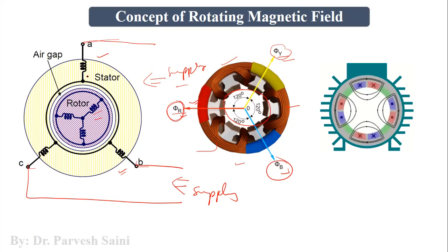All these phasors, as you can see here in this diagram, first one, these three windings are placed at 120 degrees apart from one another. They have a phase difference of 120 degrees, both on stator as well as on rotor. So the same thing has been indicated here in the second diagram for the three-phase flux. We have three phases, three phasors. For each phase we have one phasor. So these three phases are at 120 degrees from one another.